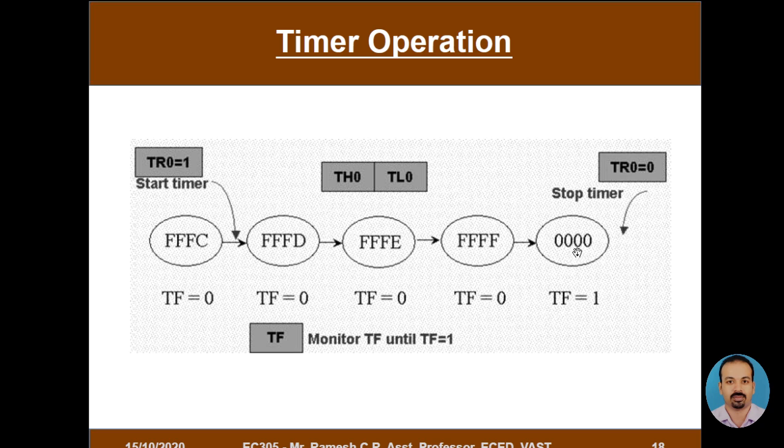On this overflow from FFFF to 0000, the timer's overflow flag will be set as 1. In all other cases it will be equal to 0. At this time you need to stop the timer.